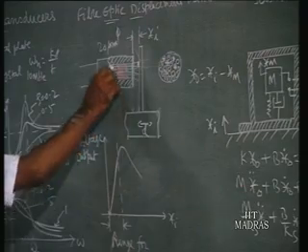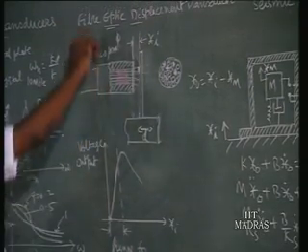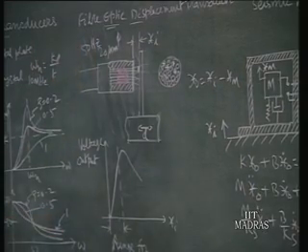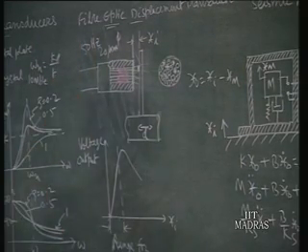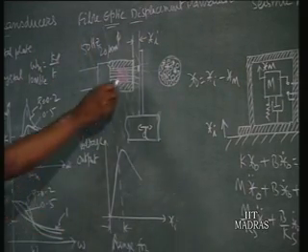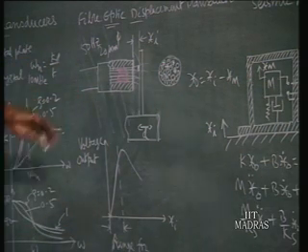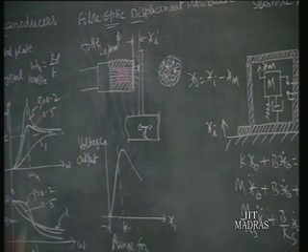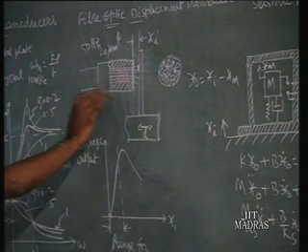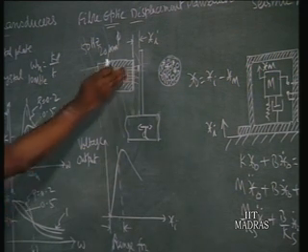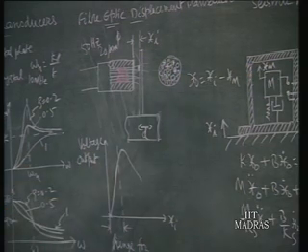The main advantage is that even if you have a 50 hertz power line nearby, it will not induce any error. That was the case in earlier instrumentation. Wherever we have a wire carrying signal, the nearby power line also induces voltage in that wire that will be superimposed over our signal, so it becomes noise. Such noise cannot be present in this type of instrumentation. It is free from such magnetic disturbances. Since it is light rays passing through, they are not affected. That is the main advantage.